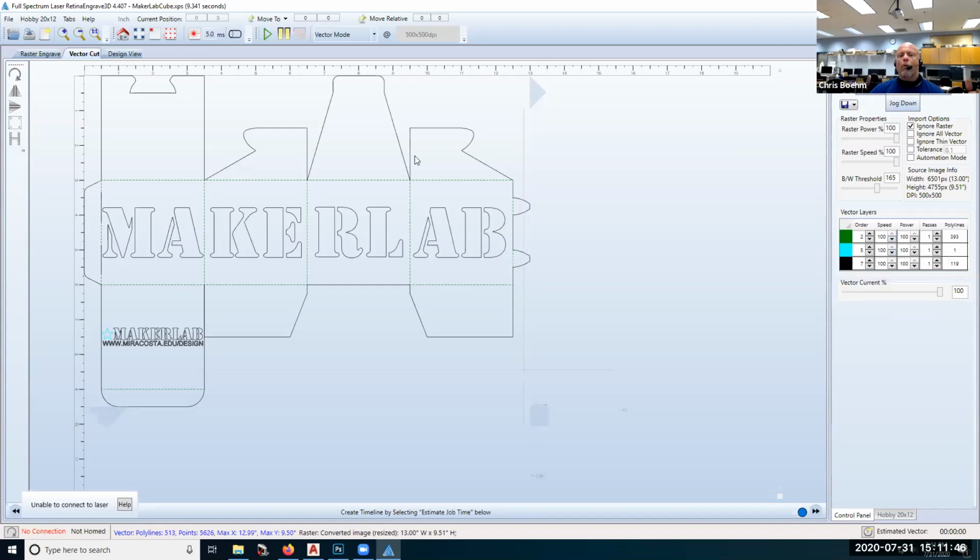For the sake of this project, I'm going to keep the speeds at 100. Obviously, the slower you take your laser, the longer it has to expose over a particular area, and so essentially, the more exposure, the more burn. That can be a good thing or a bad thing depending on the material. If it's a flammable material or something that could easily be melted, that might be problematic. If you do really want to make an impact on a piece of very dense wood, that might be a time when you slow the speed down.